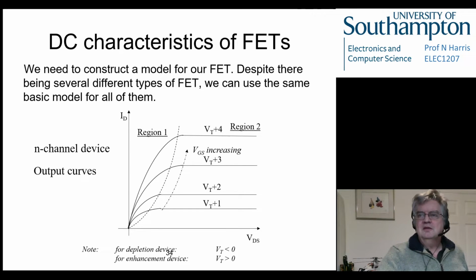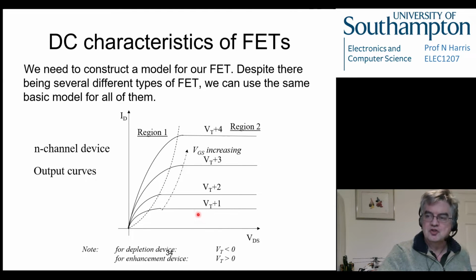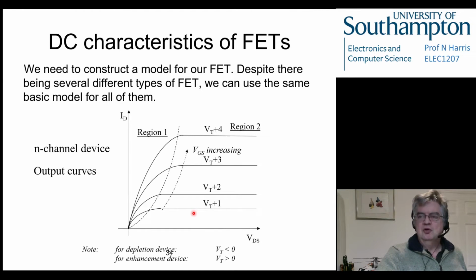So we've got an idea that the output characteristics of this field effect transistor are similar to a bipolar in many ways, in so much that there's a flat region, which is a constant current source region, where the current is controlled by a gate voltage, but it's not worrying too much about what the supply is over the device itself. So this is what makes it a current source, that the current is constant for whatever supply voltage you put across the device.